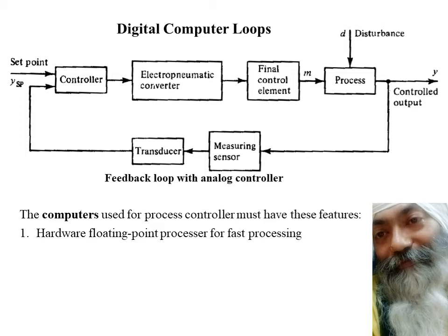Say the sampling time is not so rigorous, say 4 samples per second, which is the case in most of the process industries. So in case we have 4 samples per second, it means that we have a fixed time of 250 millisecond for acquiring the data, for processing the data, for computing the error, for computing the output, for giving it to the output P to I converter.